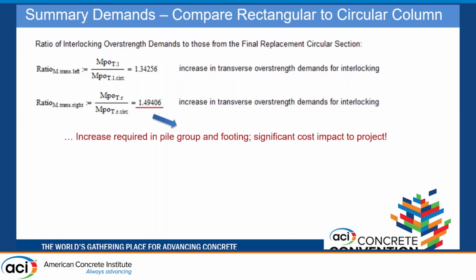So if I don't do that, and I want to get to the performance level that I'm asking for and the ductility checks I need to make, my foundations are going to start blowing up. They're going to get really expensive really fast, because I have to start increasing what's happening in the column and chase that through the substructure.